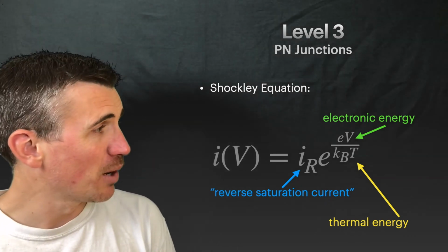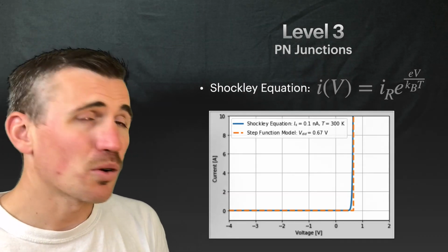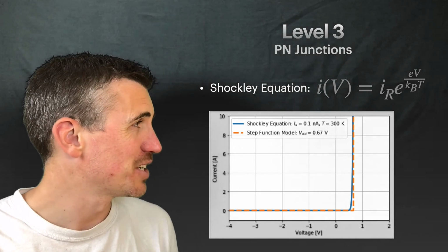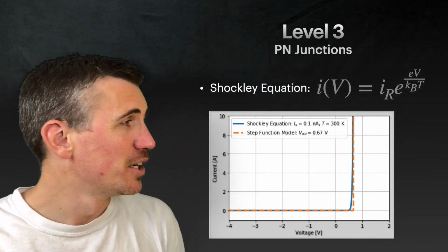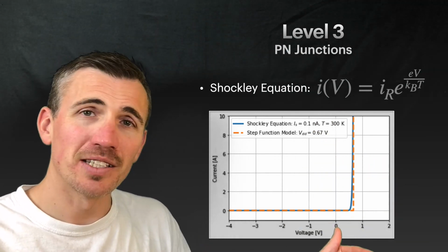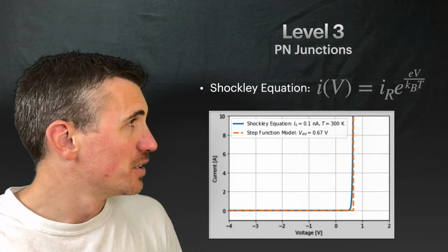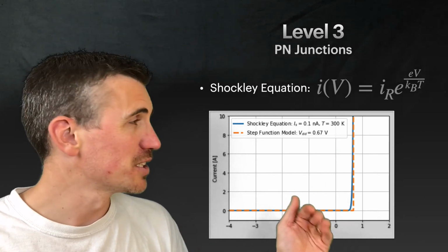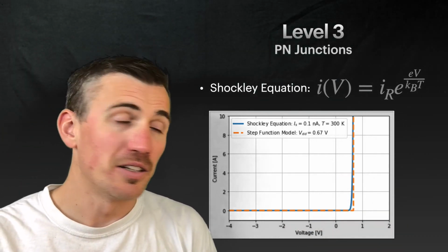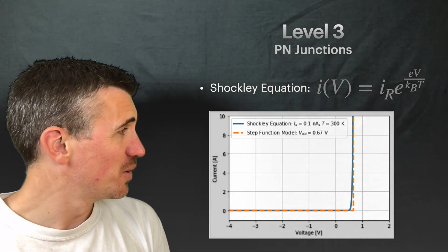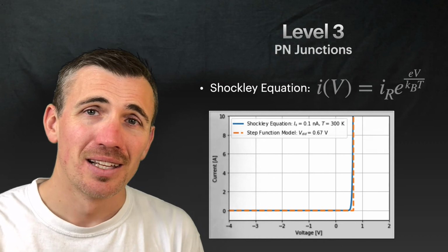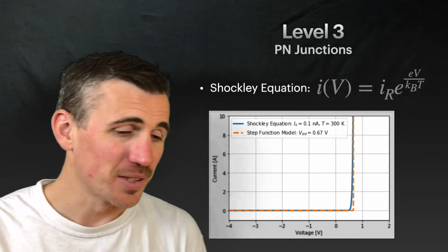And if we actually plot what that looks like, well, it's not quite an abrupt change, but it's fairly abrupt. It changes very quickly. It becomes very steep. So a current, voltage versus current, I over V is the slope. That's 1 over R. The slope is like infinity very quickly. So the resistance goes to 0 for anything well over the diode drop voltage, and the resistance goes to infinity the other way. There's like no current that flows no matter how hard we push it the other way. And this is the IV characteristic of a diode.